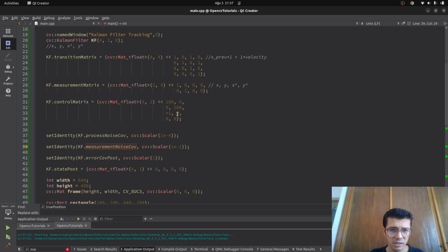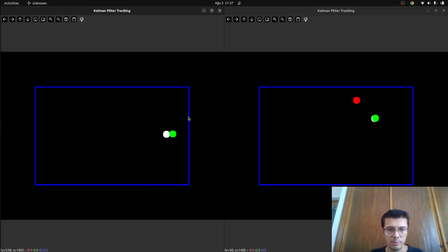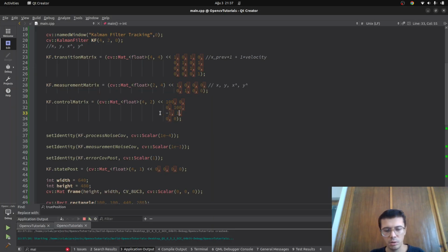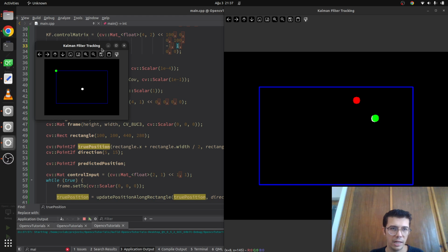This can also include the y-axis. If you put this one, I think there is not going to be a change and it will look similar to this one, because what we did currently balances each other out, so there's no effect since our speed is 5 to 5. But if you make this 15, it is considering the y-axis velocity in the x-axis velocity, so it is taking the y velocity into account in the x velocity. Now the effect should be an offset on the right side, which we are expecting.